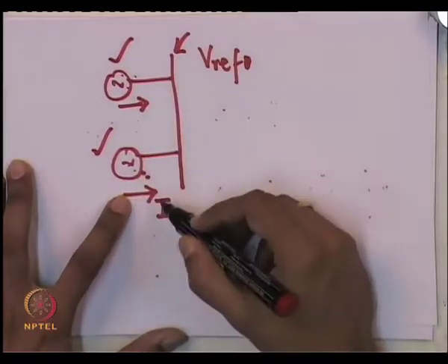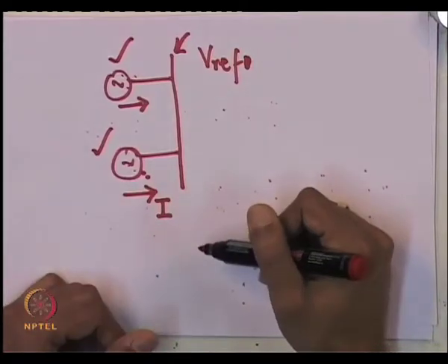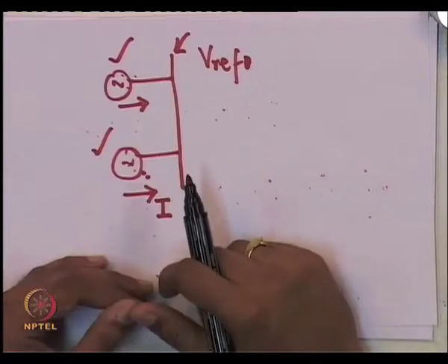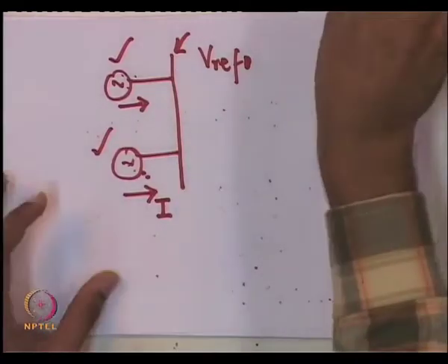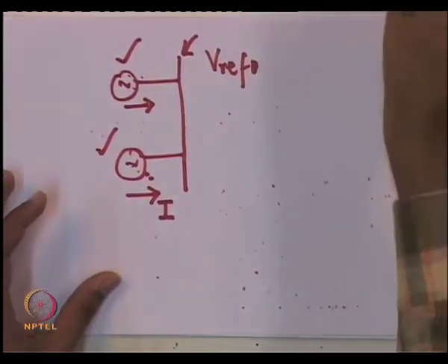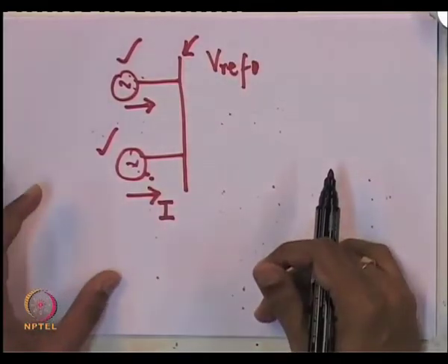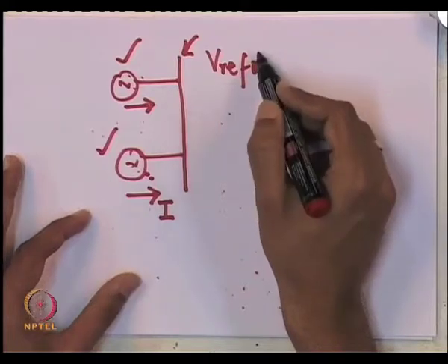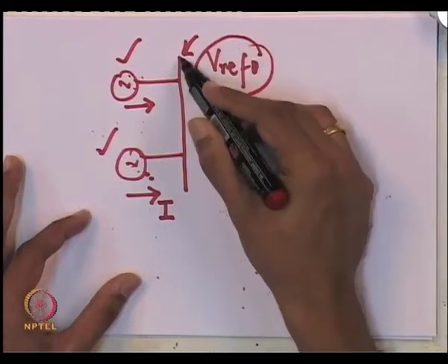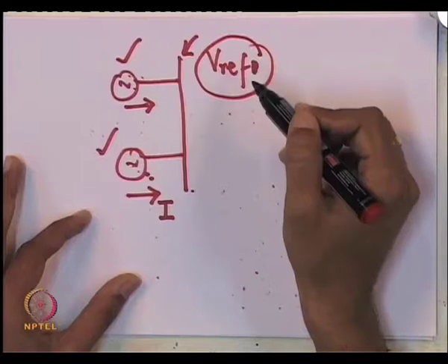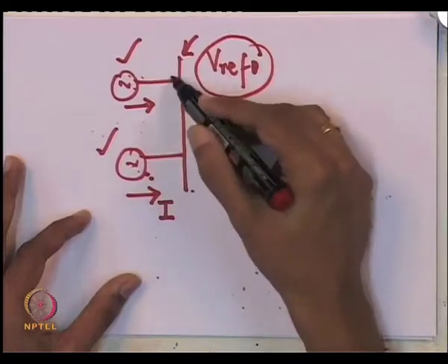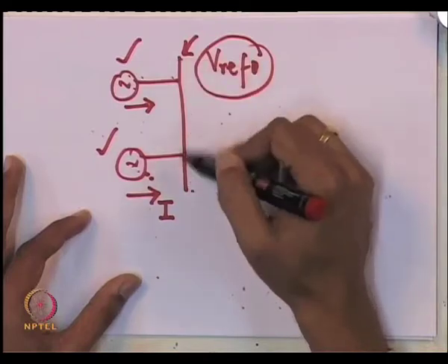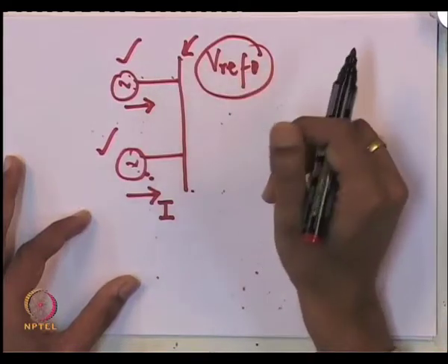Okay. So, what happens is that you make the excitation system or the exciter field voltage a function of the load current. Okay. So, if you have got two alternators or three alternators which are bused together, connected to the same bus, and your automatic voltage regulator is trying to maintain the voltage of that bus at Vref. Okay. So, each generator has got an independent voltage regulator which is trying to maintain one common bus voltage at Vref.